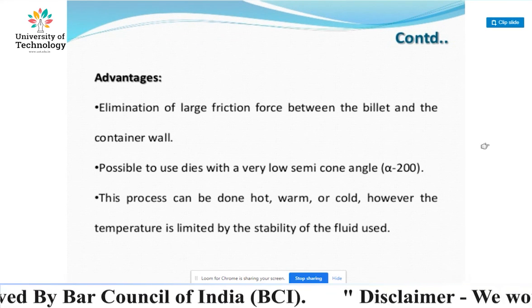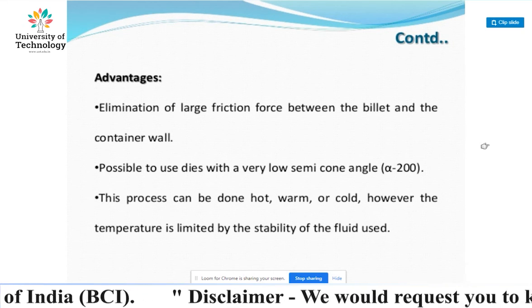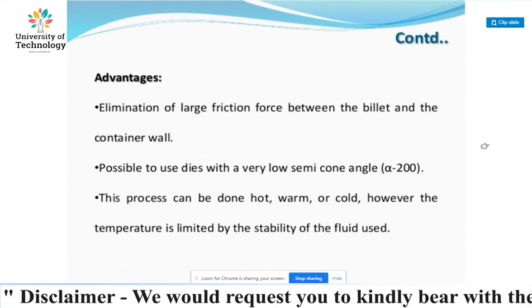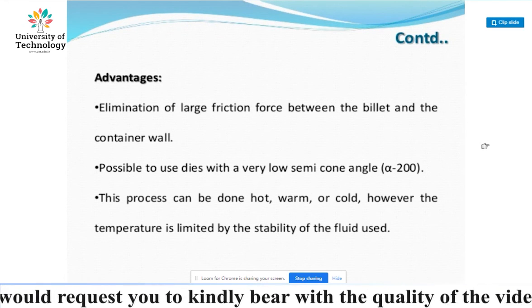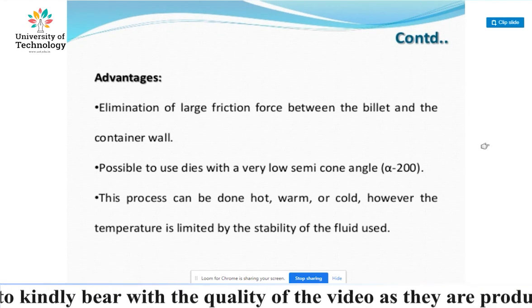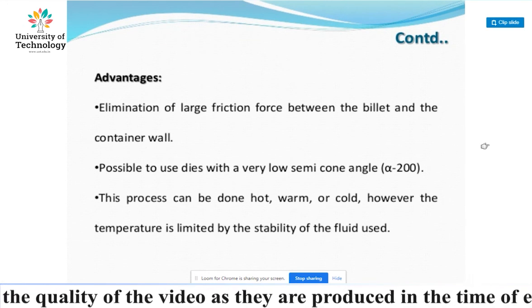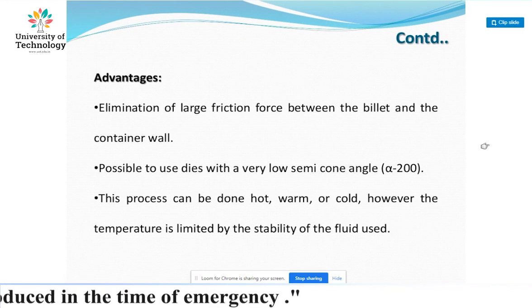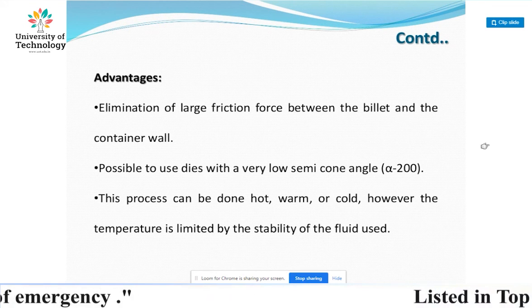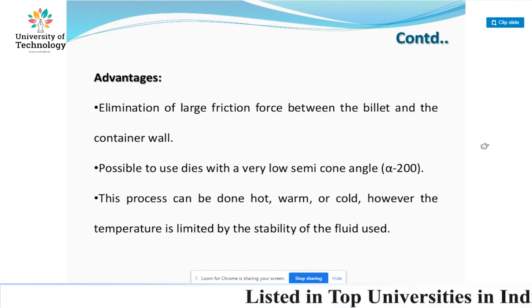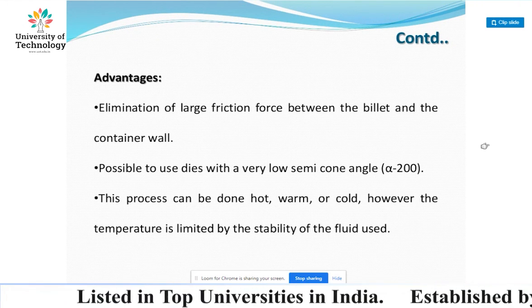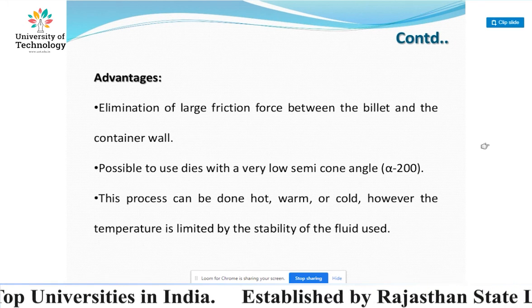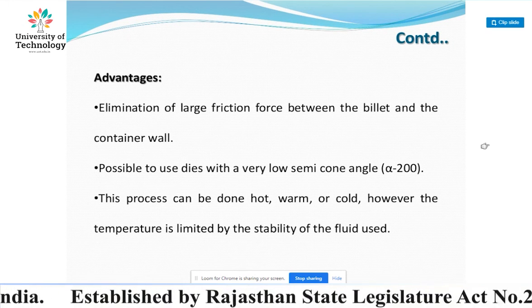Advantages of this process are the elimination of large friction force between the billet and the container wall, and it is possible to use dies with a very low semi-cone angle, approximately 20 degrees. This process can be done hot, warm, or cold. However, the temperature is limited by the stability of the fluid used.